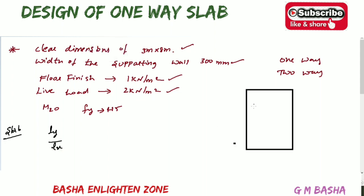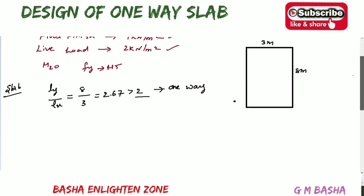Here the shorter span will be 3 meters and the longer span will be 8 meters. If you simplify this, you will get a value above 2, which is greater than 2, that is 2.67. Already people know the condition: if the longer to shorter span ratio is greater than 2, it comes under the one-way slab. If it is less than or equal to 2, it comes under the two-way slab. Then based on this you can decide the thickness of the slab.